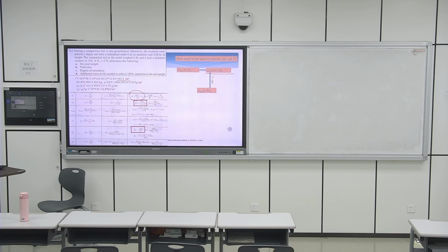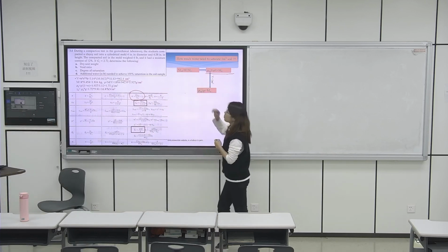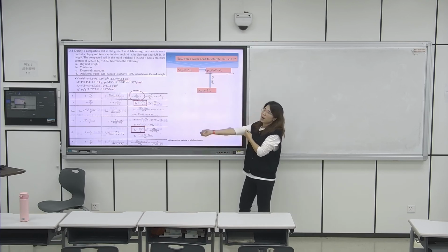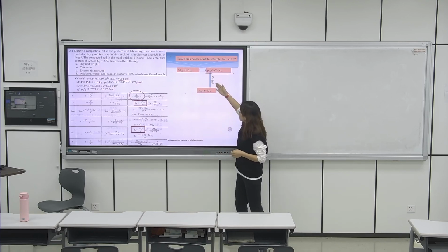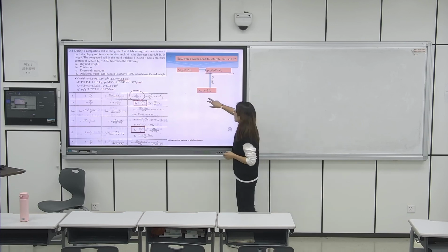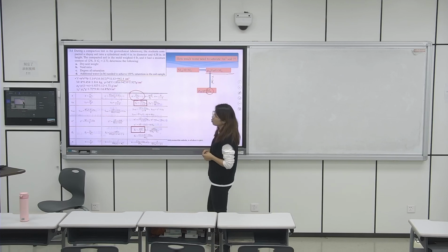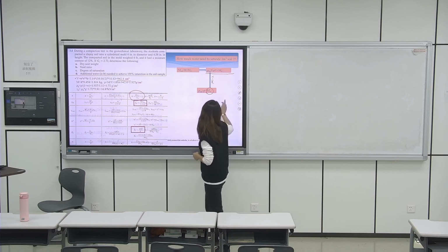Understand this? From here to here, that is because mass equals density multiplied by volume. And from here to here, that is because volume now is 1 cubic meter. So the Mw we need to saturate 1 cubic meter of soil is the difference between the saturated density and the moist density.